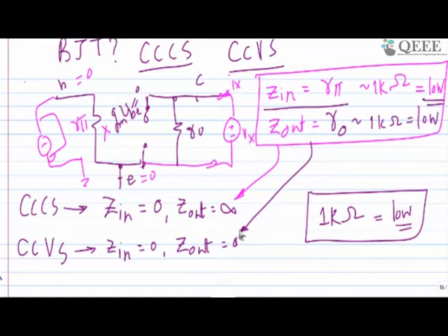So it depends how you are looking at your model. Some books say it's CCCS, some books follow CCVS, and in reality I also think it's CCVS. This is my belief. You can do a Google search. There are many opinions, because this is debated, and lots of people are following lots of things. They have lots of reasoning for that. But if we follow it on the basis of impedances, it becomes CCVS, if the early effect voltage is also included. Other than that,